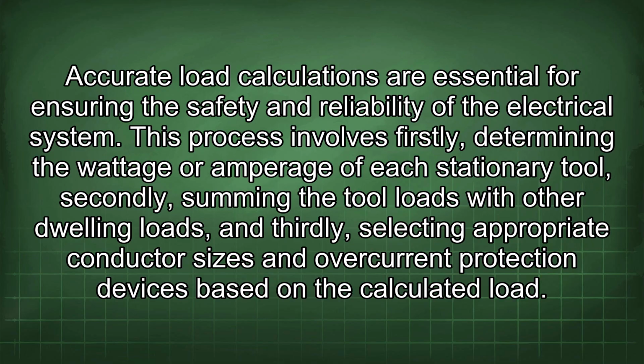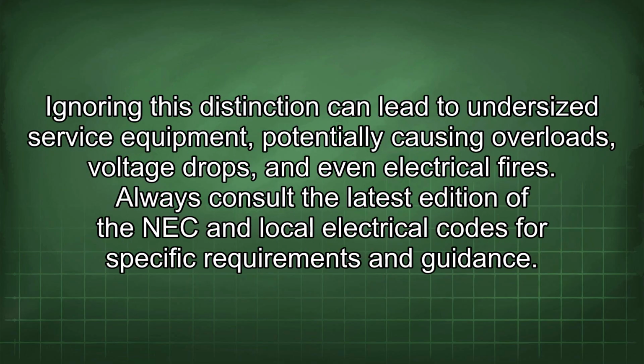This process involves firstly determining the wattage or amperage of each stationary tool, secondly, summing the tool loads with other dwelling loads, and thirdly, selecting appropriate conductor sizes and overcurrent protection devices based on the calculated load. Ignoring this distinction can lead to undersized service equipment, potentially causing overloads, voltage drops, and even electrical fires.